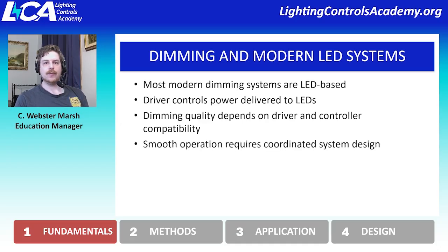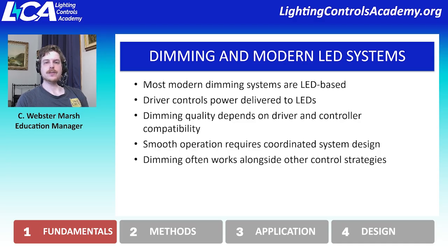So having smooth operation really requires a well-coordinated design system for those drivers and thinking through that compatibility with the driver and the controller. And so dimming often works alongside other control strategies. It's not a standalone feature that is going to work by itself. It oftentimes is going to be best coordinated with time schedule or occupancy sensing or dynamic scene control. All of this is just one piece of a much more complex lighting control system design.